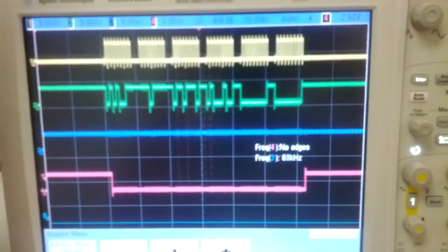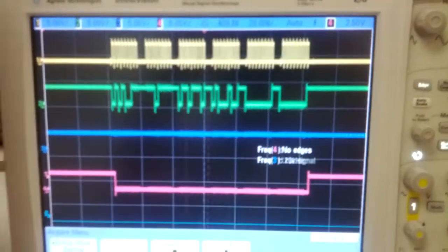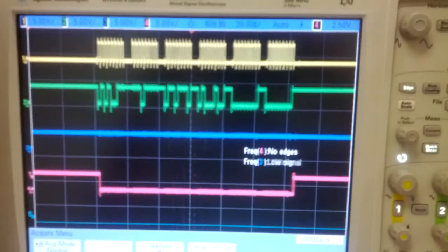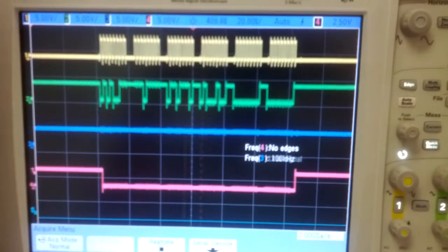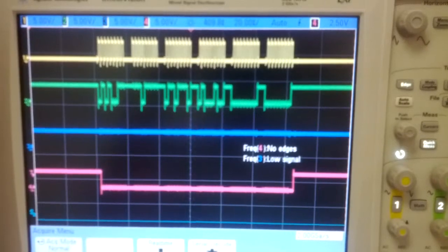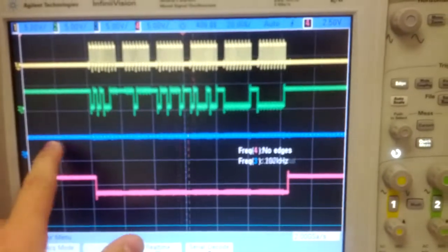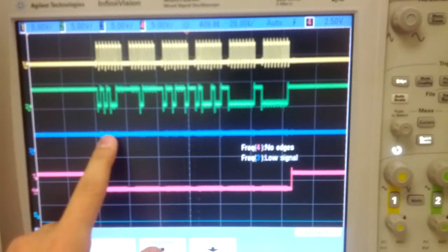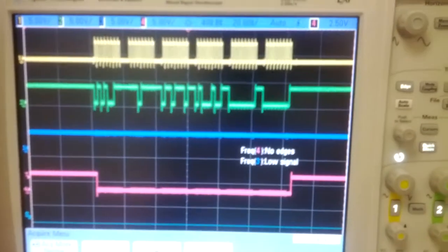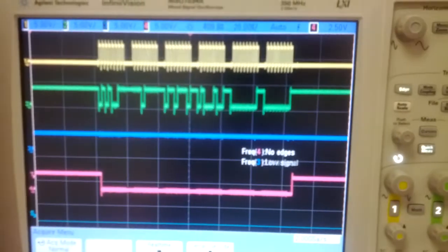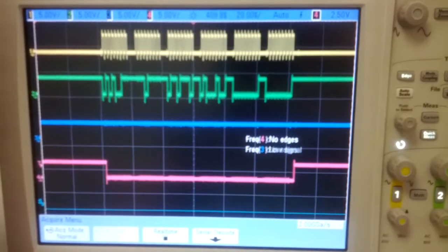Some of the things that I found that were interesting or made it difficult when first communicating to this device was that if both these slave selects are low at any point, then it doesn't know if you're writing to the SDI or SCI, and it won't perform right.